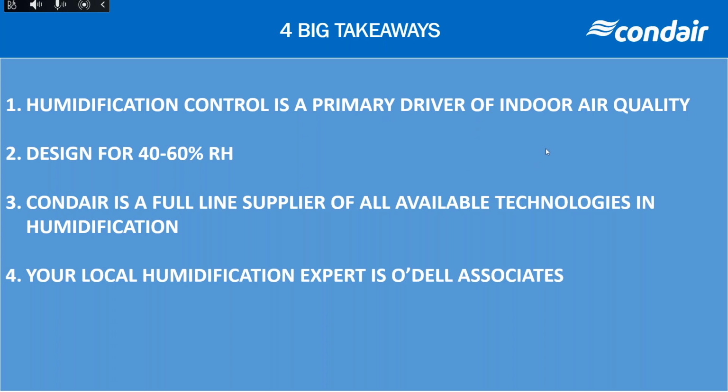Another question here: what percentage of supply air could be outdoor air or fresh air in hospitals, 10% or more? The answer to that is it depends. Administrative areas could be as low as 10 to 15% outside air, whereas other rooms, like negative pressure rooms, within the facility could be 100% outside air. So it's really dependent on how they're using that space and what it's being used for